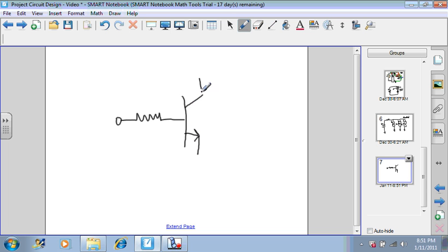But what I wanted you to be aware of is this. The part of the circuit that is connected to the microcontroller is pretty standard. You connect it here through a resistor value. A typical value might be 1 kilo ohm, and you're done. Usually 1 kilo ohm with a 5-volt source is more than enough base current to push this transistor into saturation.